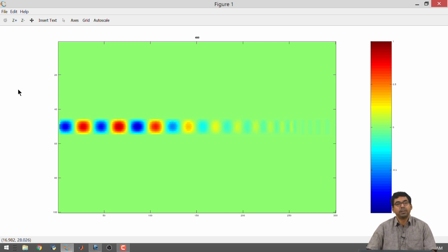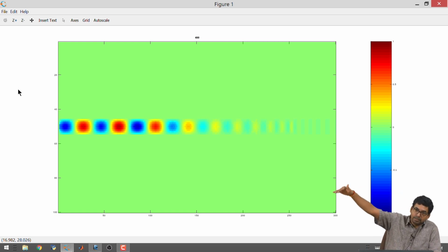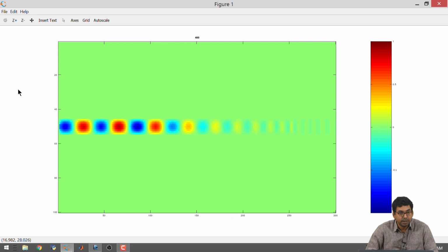Okay, clearly I am noticing something odd happening over here. I have a source, and as it travels through the waveguide, I notice there is an attenuation of some kind. So first, it gives me a clue that maybe there exists a cutoff frequency for this waveguide, and maybe we are just above it, or very closely approaching the cutoff frequency.